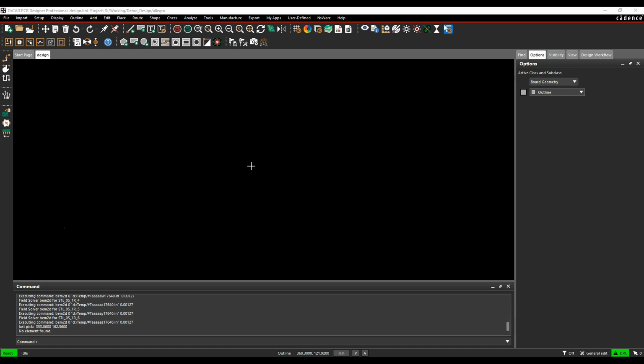We actually use two material files. There's a materials.dat or CMX file, which is where you store all the default materials, and then there's something called a site file, a layer materials.xml file, which stores if you're building mask materials, so if you wanted to include things like silk screens or cover lays or any specific coatings that you need for flexi-rigid style designs, and I'll show you how to edit both of those files as well.